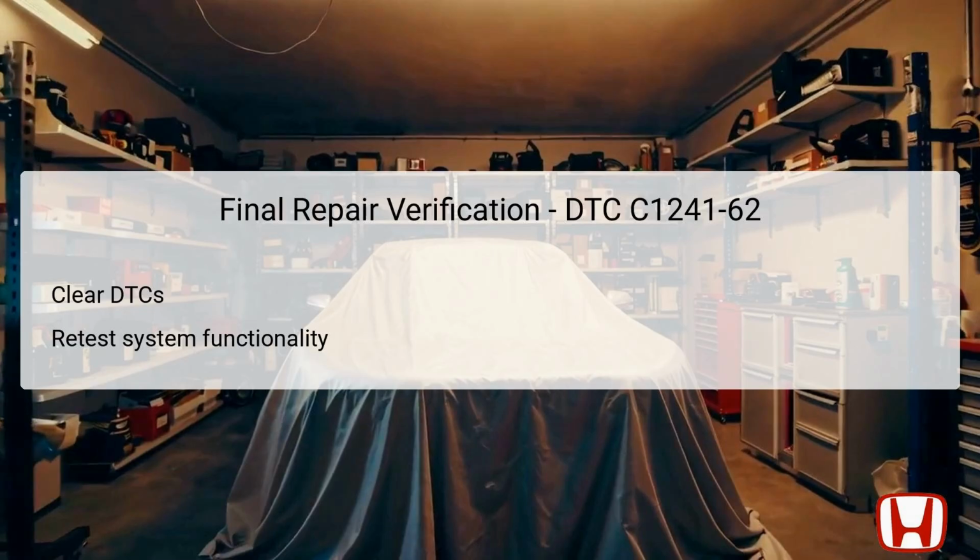Following that, retest the entire brake system to confirm its functionality. During this test, monitor the performance of the brake booster pressure sensors and their responses under varying conditions. A successful verification process indicates that the original issue has been resolved, ensuring that the braking system operates correctly and safely.